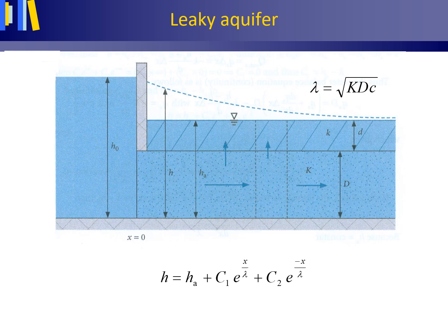For both finite and infinite polders, a finite polder being a polder with a fixed boundary condition to the right, we will see an example of this slightly later on, the hydraulic head distribution with horizontal distance x in the aquifer, thus the potentiometric surface shown as a dashed line in this figure, can be determined from the water balance of this column, or rather rectangle of the subsurface, and then described as explained in full detail in section M3 of my book by the following equation.